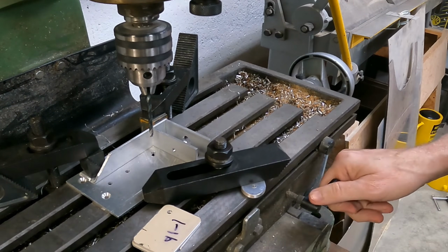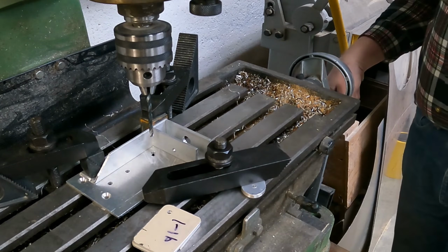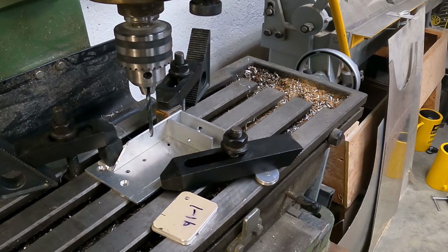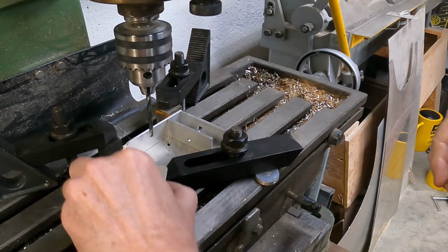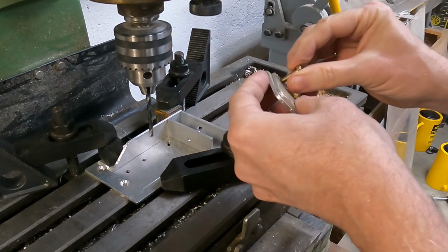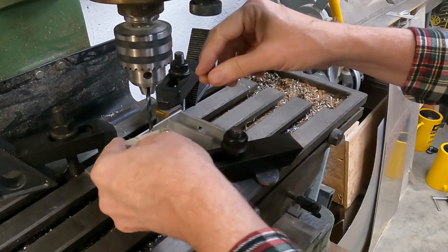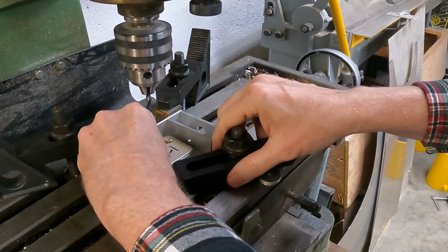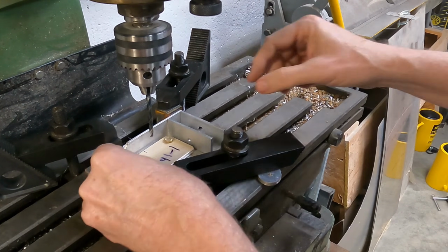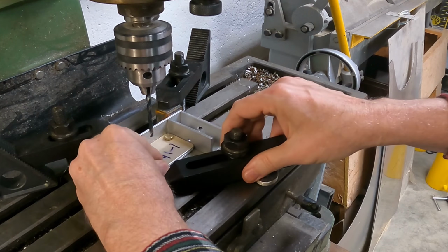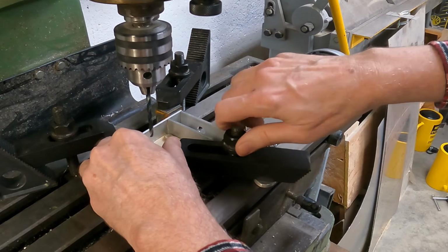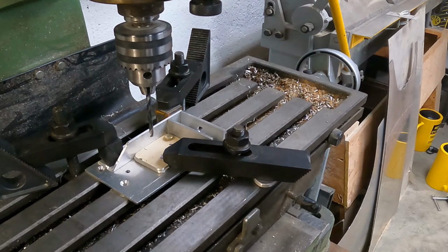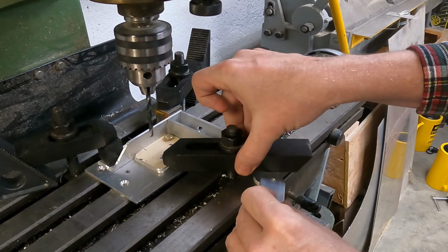It's time to drill the second hole in the load spreaders. Now this is going to be the second hole at the bottom of the spreaders after the first hole that we drilled. And I'm calling this position number 2. At least it's position number 2 in the spreadsheets and the diagrams I've made. So this hole is going to be a different spot for each pair of spreaders, just because that's how it worked out. Now I'm going to use the same fixture that I was just using for the first hole. So I'll put a bolt through that hole that I just drilled in the spreaders and through that same hole in the fixture in order to hold the spreader in the right spot.